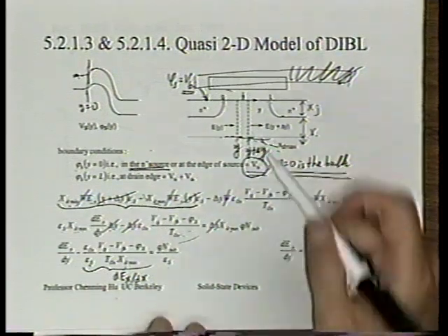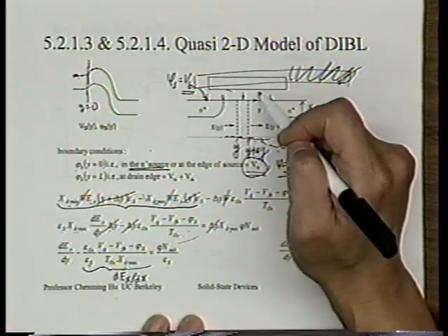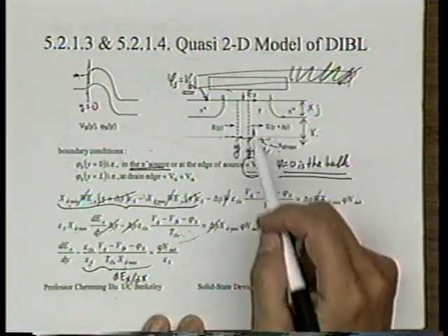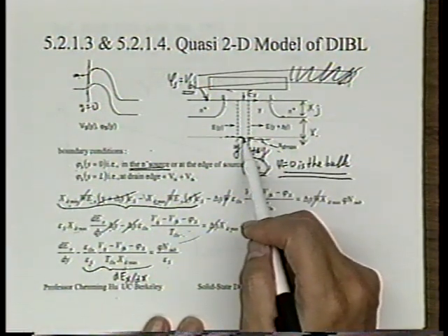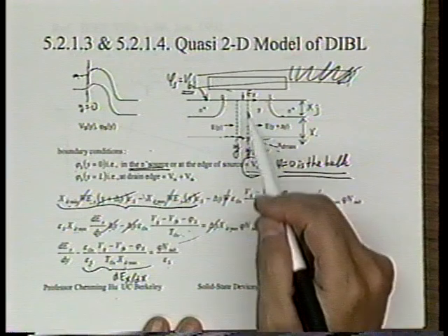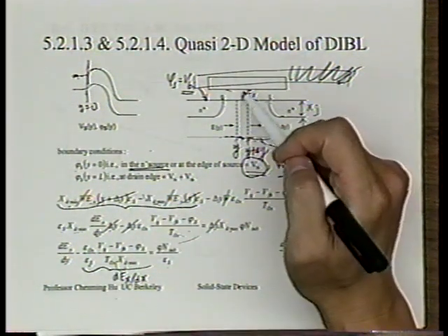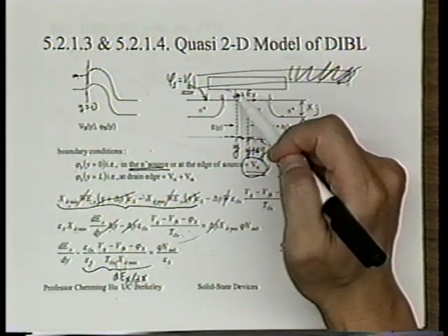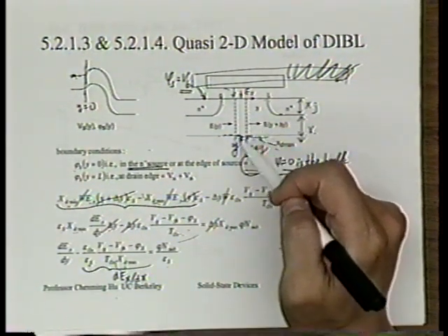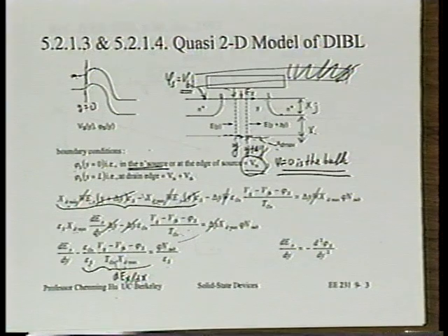It's because any electric field Ex becomes 0 by the time we get to xd max, right? So dEx/dx should be inversely proportional to xd max. Whatever Ex we have, which is really E0x, will gradually decrease until it's 0 at xd max. So you can see this term can be interpreted as dEx/dx, but we came from this Gauss' law consideration.